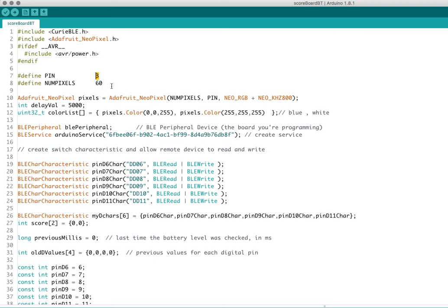There's really not a lot of setup because all we have is the Arduino and LEDs hooked up. This is an initialization for the NeoPixels. You just tell it the order of RGB. Some of them are GRB, or kind of weird stuff like that. Give it the pin number, which we defined up here. And then down here, I'm setting an array of 2 different colors. So blue and white, I've got it listed down here at the end. And those are just for the different teams. So if you want to change the color of the team colors, this is the line that you do it in. If that's all you need, you're good to go.